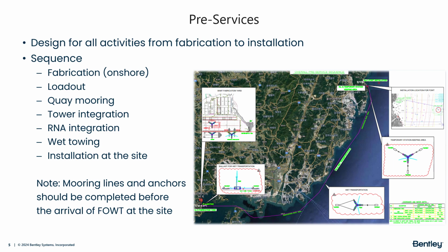Then it is lowered to make it float freely using the buoyancy difference. During this stage, ensuring both structural integrity and hydrostatic stability is very important. Once the floater is at sea, it is temporarily moored to the quay for the installation of the tower and RNA, rotor nacelle assembly.